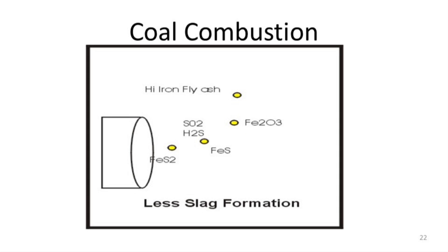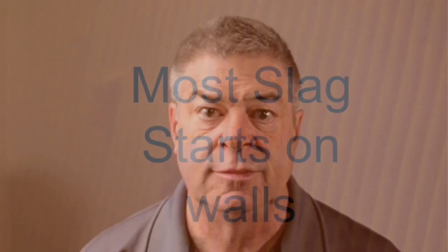So just keep in mind that if this is the case, you would prefer a higher calorific value coal. The low calorific value coals require quite a bit of coal flow to make the load, and then the corresponding air to fuel ratio is probably set at 1.8 or 2. So we get into a situation where lower calorific value coals are increasing the pipe velocity. There also is the chance that at higher coal flows, the fineness deteriorates, so you get more coarse particles.